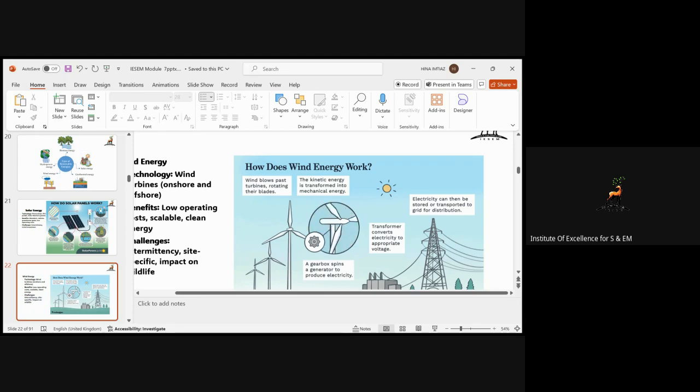So the air pressure built between these blades, on one side of these blades is high air pressure, on the other side there is low air pressure. So the air pressure basically results in generating lift and drag, and always the lift is on the high surface and the lift is basically stronger than the drag, which causes the rotor to spin.